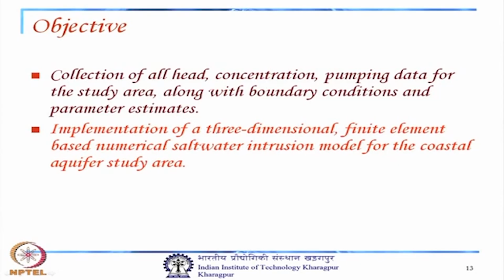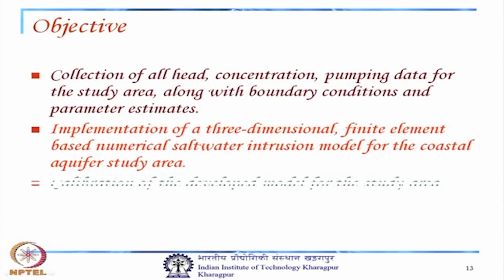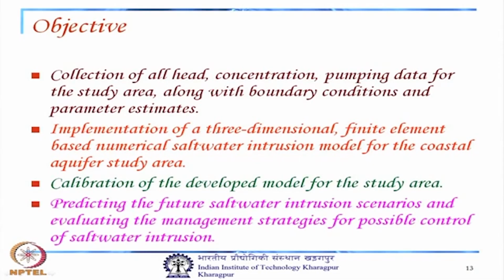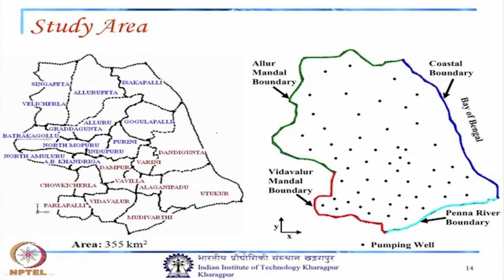Next is implementation of a 3-dimensional finite element based numerical saltwater intrusion model for the coastal aquifer study area, and calibration of the developed model for the study area, and predicting the future saltwater intrusion scenarios and evaluating the management strategies for possible control of saltwater intrusion.